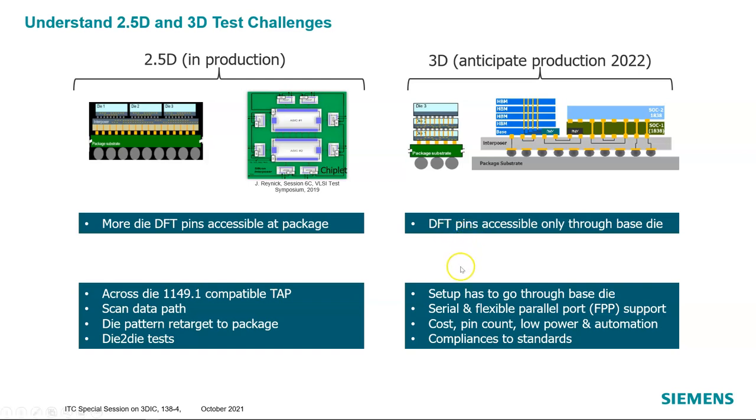The requirements, for example, are how to make sure that the full coverage tests are consistent between a die test at the wafer and inside the stack. Usually, we don't have enough pads that can be directly probed by the ATE. How do the dies communicate with each other through a standardized infrastructure and protocol? How to efficiently perform die-to-die test inside the stack?